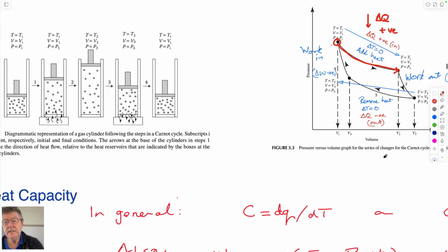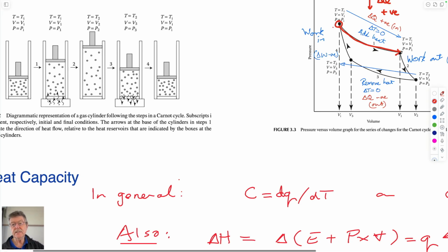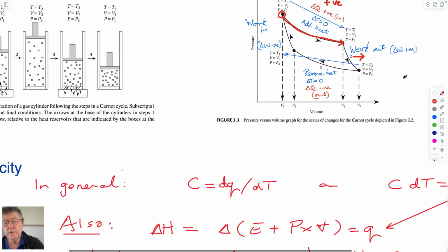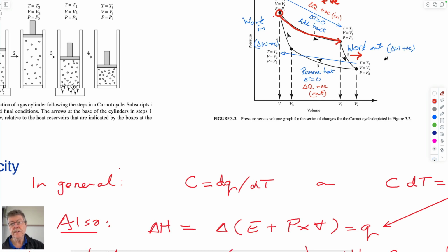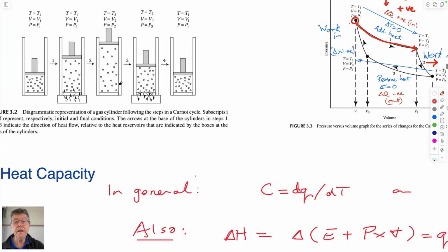Once it is heated, then it is allowed to expand. So it gains heat, it expands with that heat. By expanding, it puts work out of the system. And so work out of the system would be negative by our sign convention, not positive, which allows it to be running it through a turbine. So it expands and runs through a turbine, comes out the other side as a vapor instead of as a liquid as it started out. So by the time it gets here, it's a vapor.